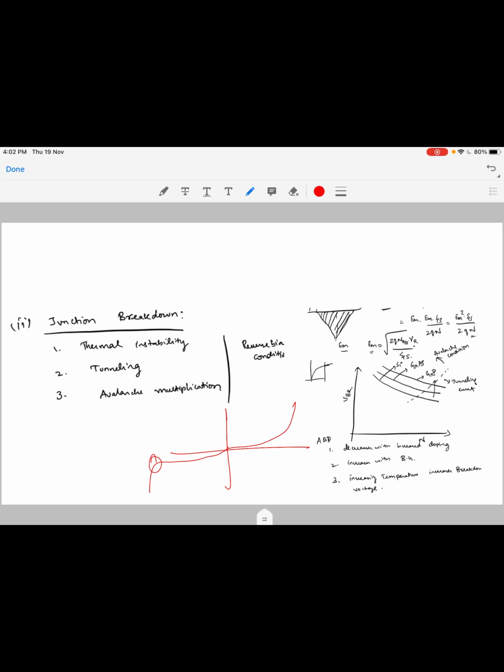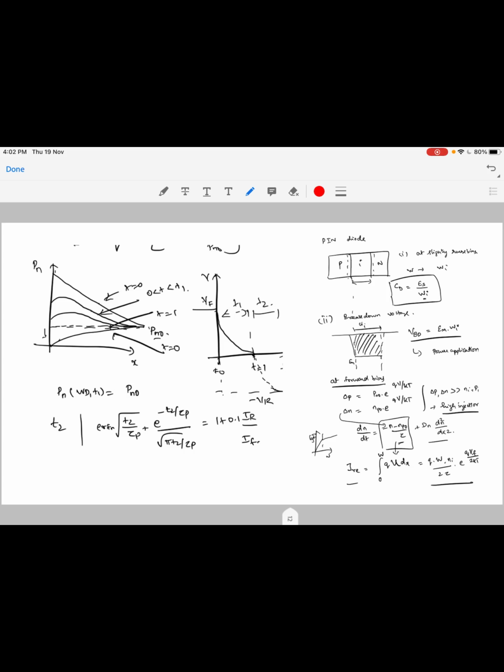Finally, we saw some interesting aspects of what happens if you switch a diode from reverse to forward and forward to reverse. We showed that when you have a diode operating at forward bias and then quickly turn it to reverse bias, it will not be able to turn off the current very quickly, and hence you will have the current display this kind of dynamics.